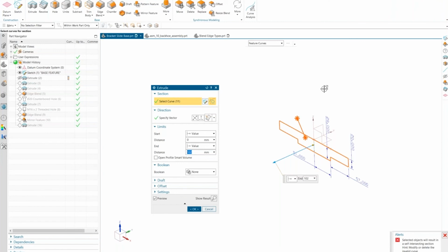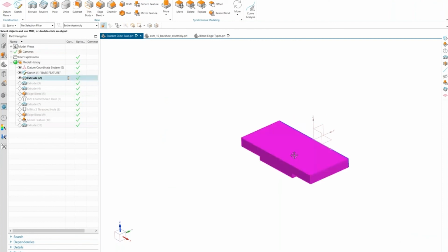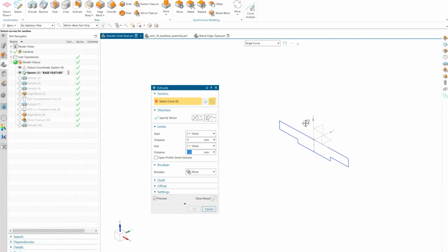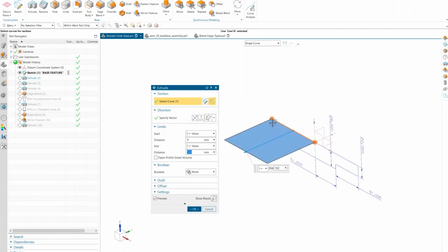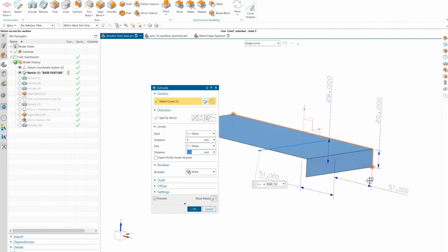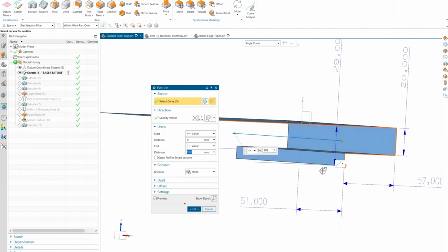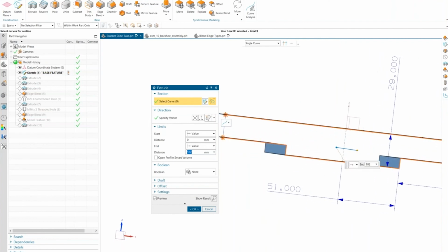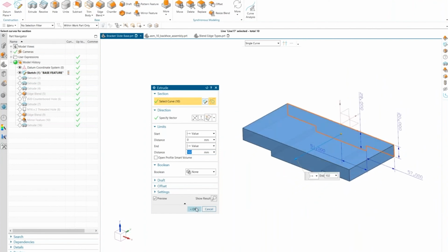I can't create the thing they're telling me to create. So it's giving me an alert there, so I can cancel out of that. Let's say I need that line. What I can do is change my selection intent and then shift select my previous selection. And now instead of the sketch curves, the feature itself, I'm just adding single curves. So I'm just going around adding those single curves that happen to be in a sketch, but they're the same curves I was using previously. They're just selected in a different way. So now I can click OK.